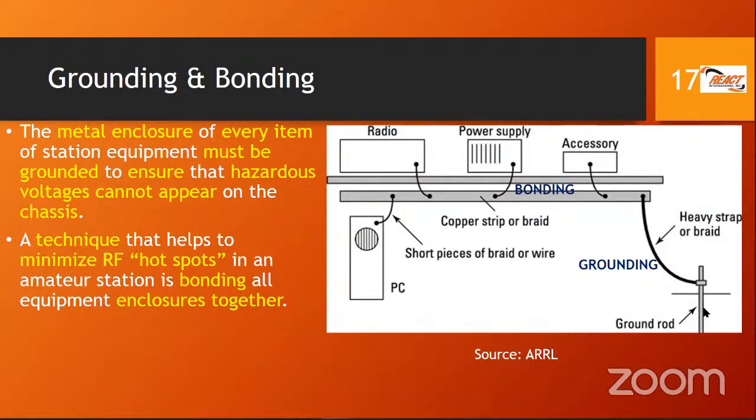You should not have an isolated ground rod. That is not correct according to the NEC and most electrical codes. So anyhow, you have your ground rod in your station. It's usually outside, not too far from the shack or the house or the location wherever you're at. If it's a portable operation, you drive that ground stake into the ground, and that is your ground.